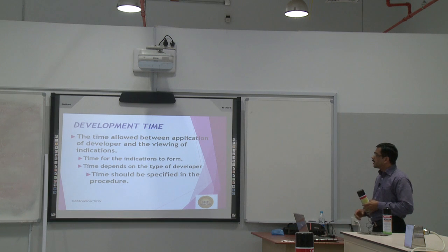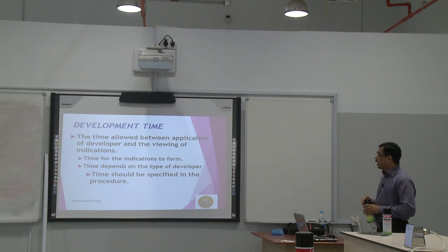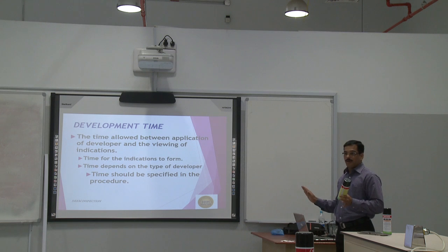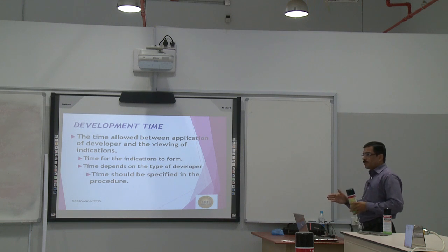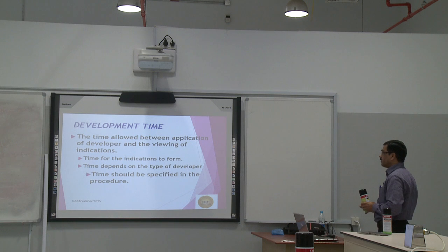Next is the development time: the time allowed between application of developer and viewing of indication. That is not as important as the dwell time, but for development time we wait for the developer to dry. As it is a non-aqueous developer, it dries immediately. When you apply the developer, it dries in the same second. From that point onwards we can start our interpretation, so there is no need to wait.